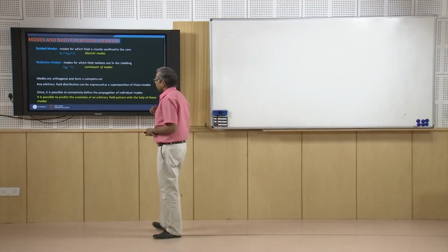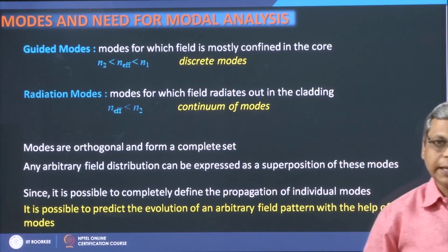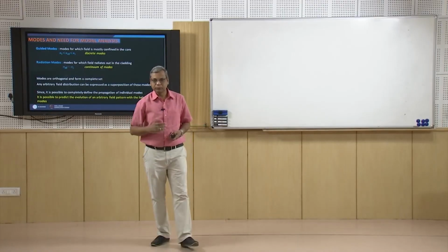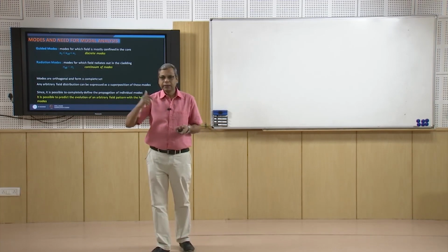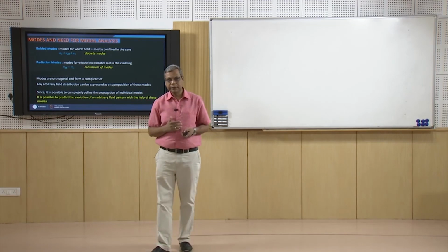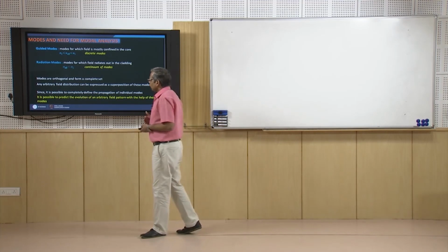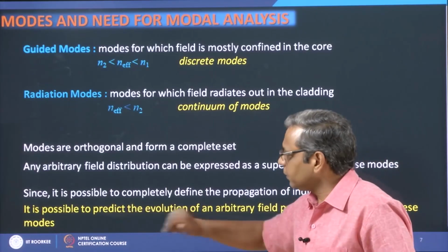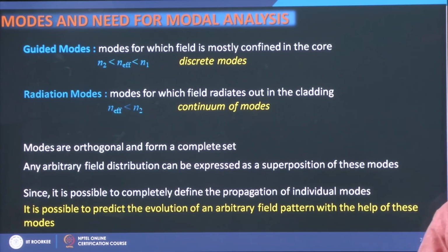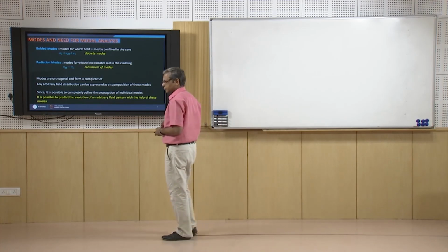And since it is possible to completely define the propagation of these modes, I know the propagation characteristics of these modes: how they propagate in a fiber, what the field patterns are, what their respective effective indices and correspondingly velocities are. Then it is possible to predict the evolution of any arbitrary field pattern when it propagates in an optical fiber. So, that is why understanding of modes is very important.